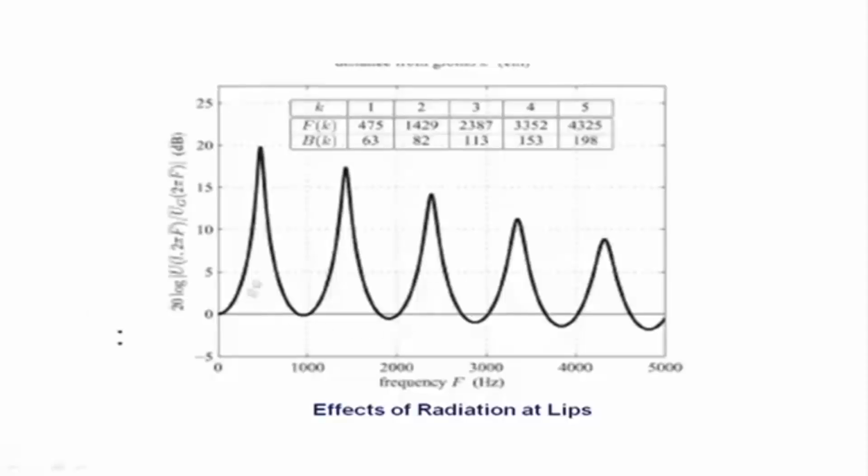Okay. So, this is the frequency response of the uniform tube. If I consider the whole vocal tract as a single tube, then this is the transfer function of the single tube model, where the formant frequencies are 500 Hz, 1.5 kilohertz, 2.5 kilohertz, but the high frequencies are attenuated due to the radiation loss, and it is not zero bandwidth if I consider the losses inside the tube.